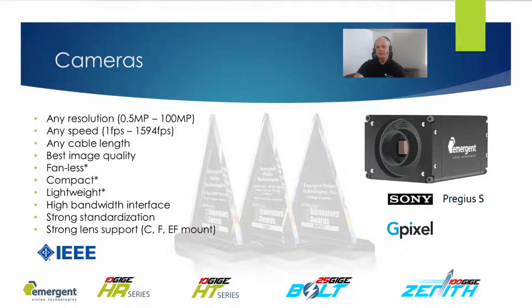Frame rate for typical systems range from 30 frames per second at 100 megapixels to 100 frames per second at 12 megapixels. The choice of frame rate is based upon the temporal or time accuracy required. Faster moving subjects naturally need higher temporal accuracy and thus higher frame rates.